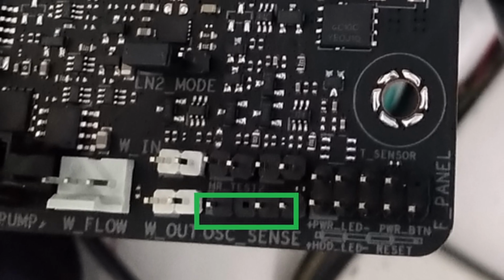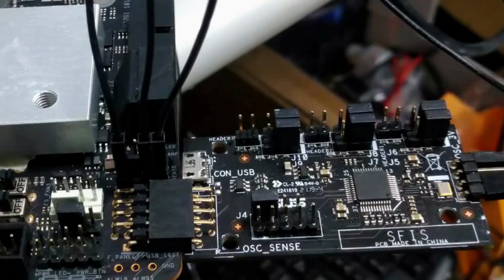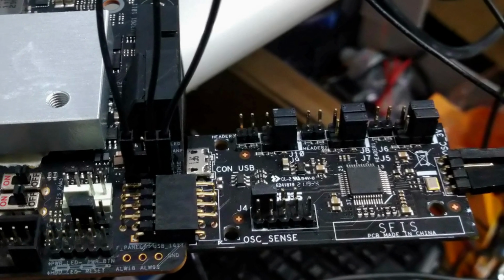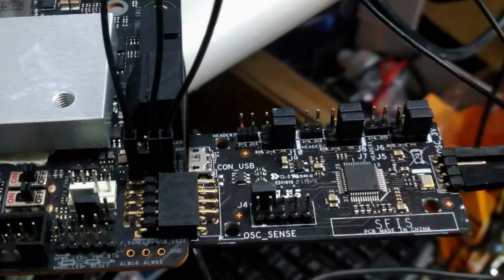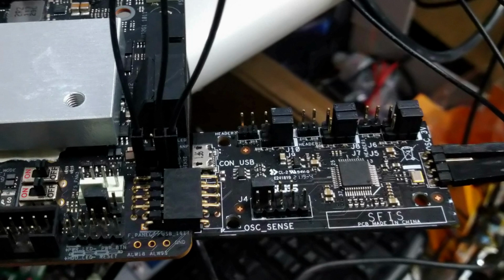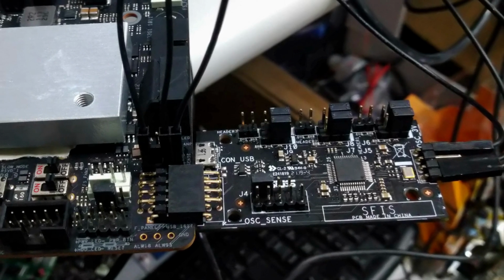The Voltician is a USB oscilloscope. You can use it on your system directly or connect it via USB to a second system. The 2 options require a slightly different setup. If you want to use the Voltician to check the voltages on your system, simply plug the device into an available USB header on the motherboard. Then connect the 3 channel inputs to the OSC Sense pin headers on the motherboard.